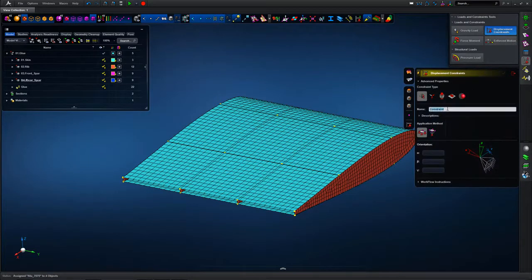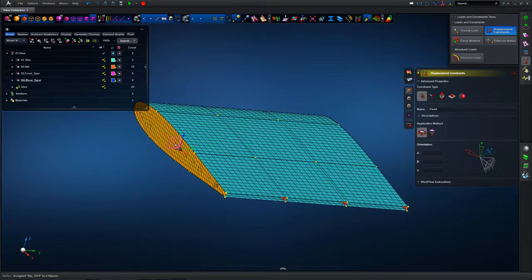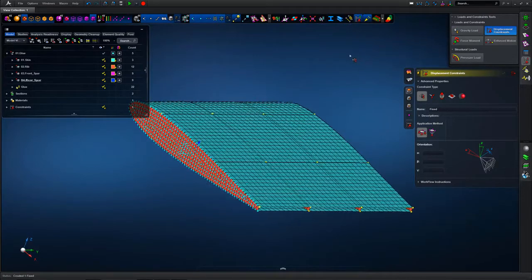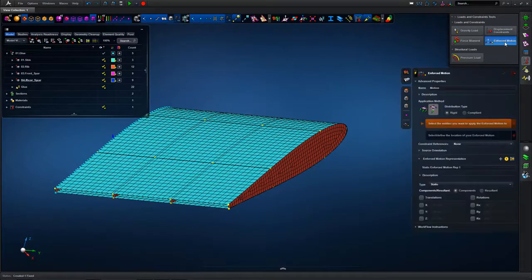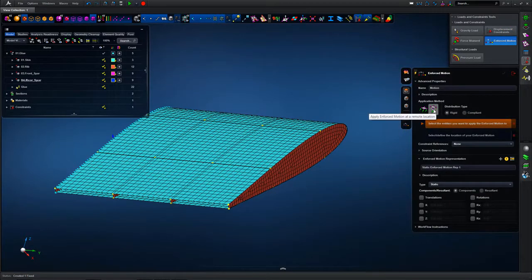So if you remember, we had the thicknesses defined from the mid-surface definition. We now have material properties defined, and we're putting in some simplified loading in the structure just to show how the loads transfer across the glued interfaces. So glue contact is a good technique. It's very quick to tie similar meshes together to allow us to do what-if studies or trade studies.